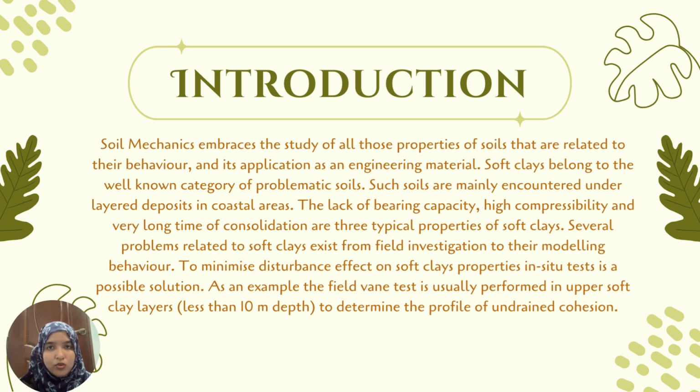Several problems related to soft clay exist from field investigation to their modeling behavior. To minimize disturbance effect on soft clays properties, in situ test is a possible solution. As an example, the field vane test is usually performed in upper soft clay layers less than 10 meter depth to determine the profile of undrained cohesion.